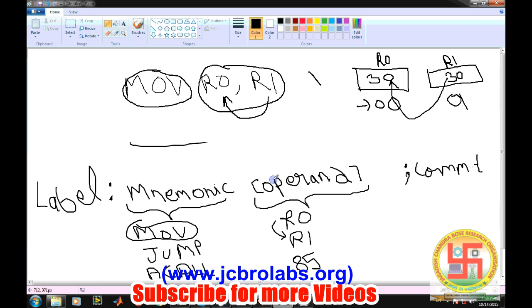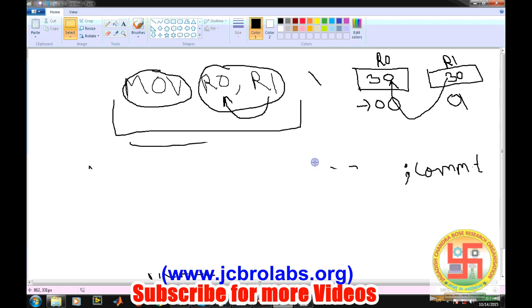Now moving forward, this makes a complete instruction for the 8051 microcontroller. Each instruction has some size as well as some time it takes to perform. If we talk about the size, ultimately this instruction is going to be stored in the microcontroller. Most of the instructions are 2 bytes, that means 1 byte for the instruction and 1 byte for storing the addresses of R0 and R1. So these are 2 byte operations.